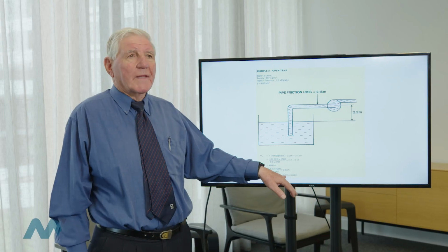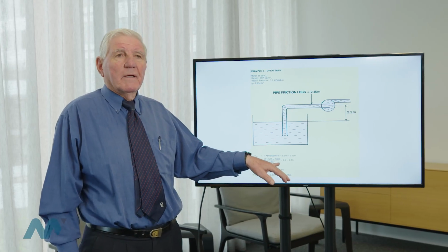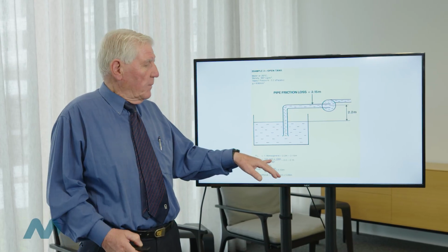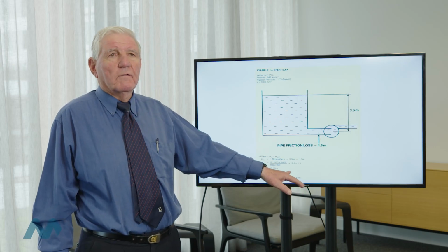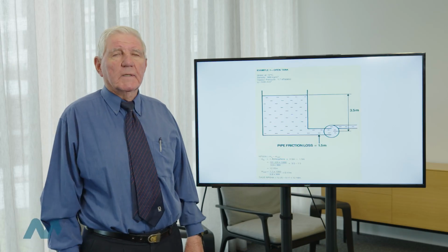So we would normally look at the worst case scenario because we're never sure exactly where the pump is going to be operating along the curve. So if we see that the worst case NPSHR is 6 meters, we'd be in trouble with that pump if it was on suction lift. But if we go back to the suction head, then an NPSHR of 6 meters is easily accommodated.